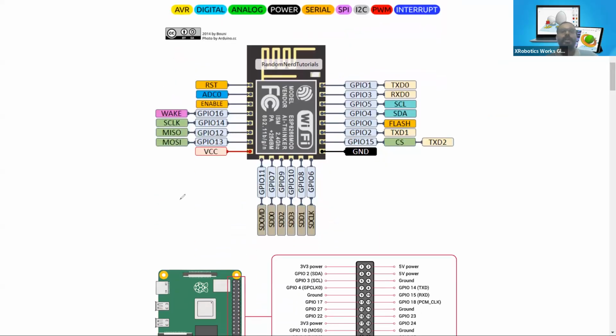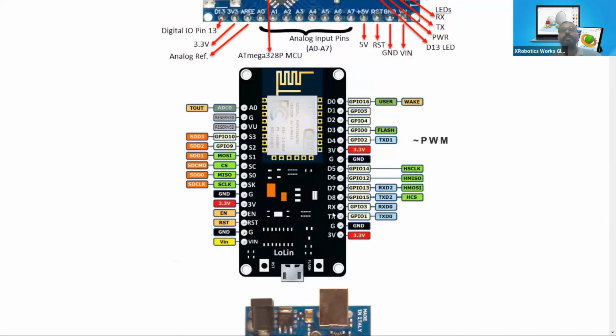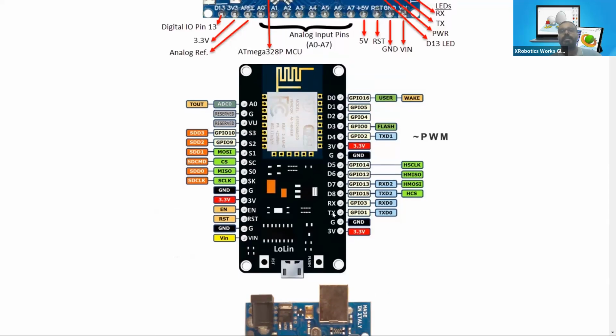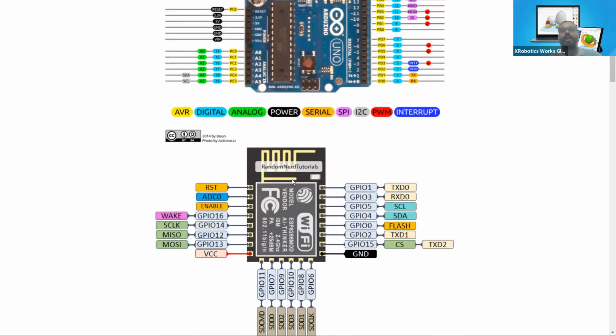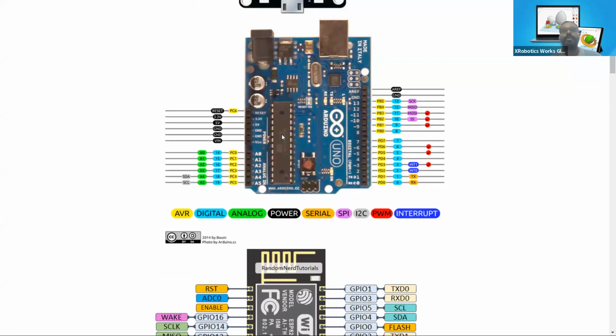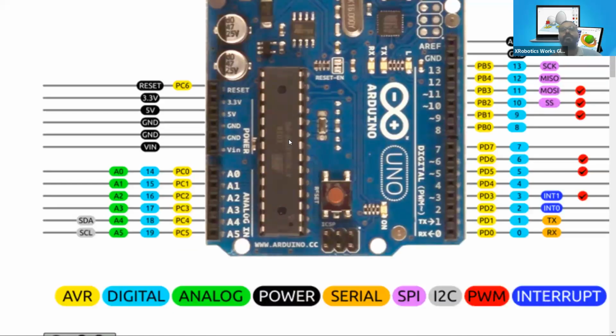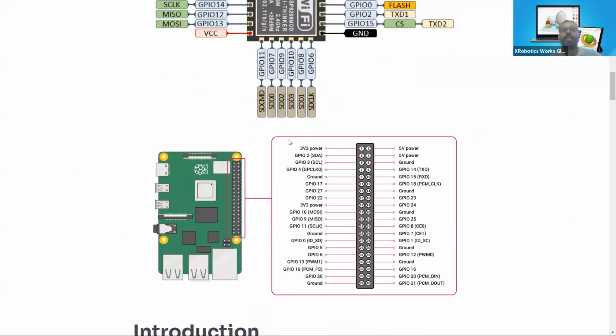Earlier I explained the NodeMCU. The NodeMCU has a microcontroller embedded into it, the ESP8266. The size of this one is only the microcontroller, but apart from this, what we had on our NodeMCU board is the development board. You can see clearly the difference, as the NodeMCU development board contains many more things compared to the normal microcontroller. And if we take the microcontroller out of the Arduino itself, like this IC from this board, then we will see the similarities between the microcontroller and the development board.